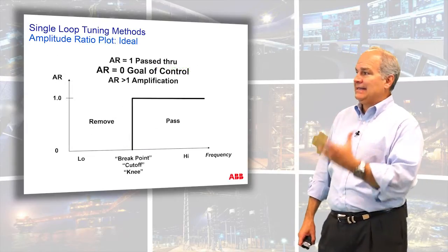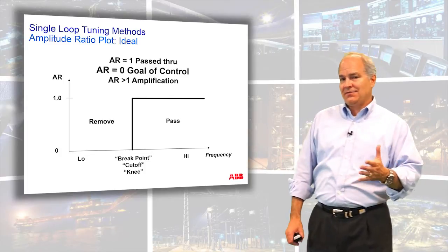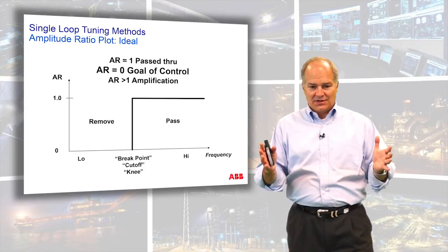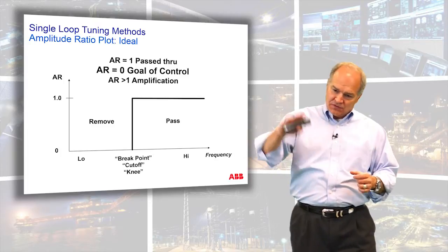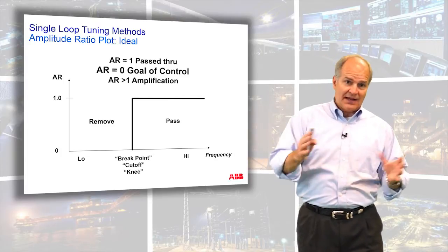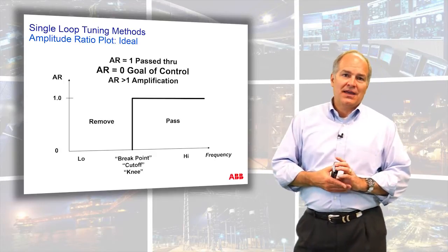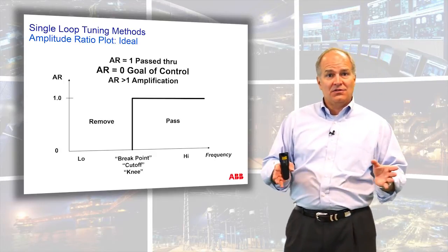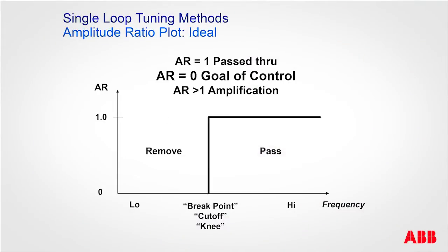In an ideal attenuation curve, now imagine if you could do this, you set up a signal conditioner and you could cause your process to change at a really slow frequency and then you get faster and faster and you can measure it. That's not really possible. In some of the simulators we have and in some of the labs we actually do that. But I want to show you the ideal example. Over here we have this point beyond which our controller can't do anything.